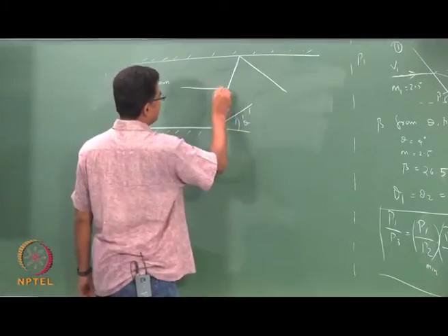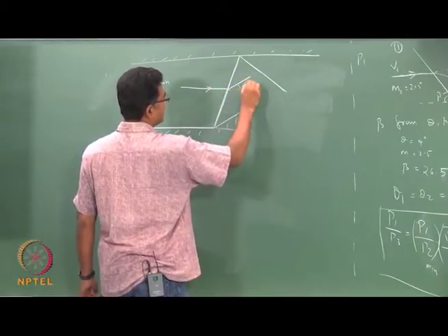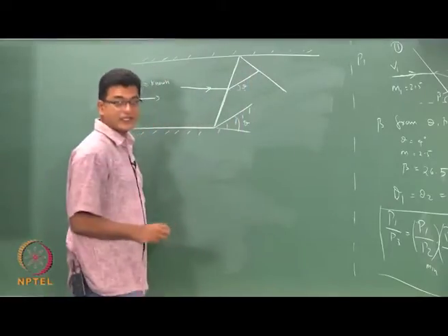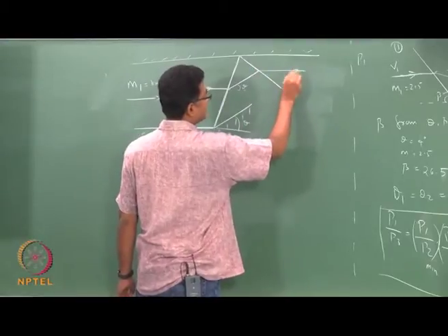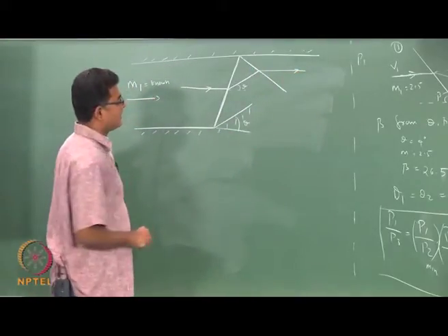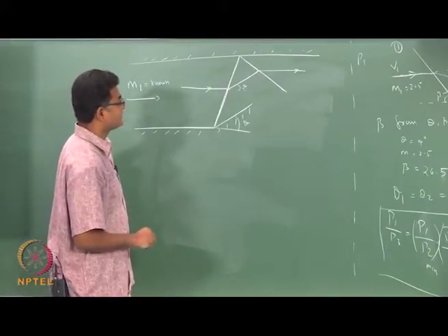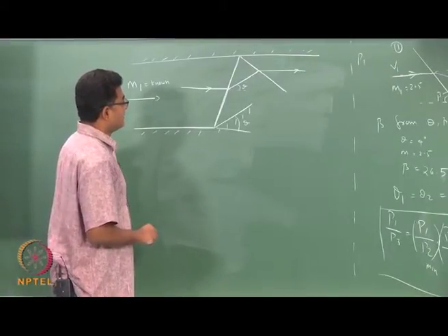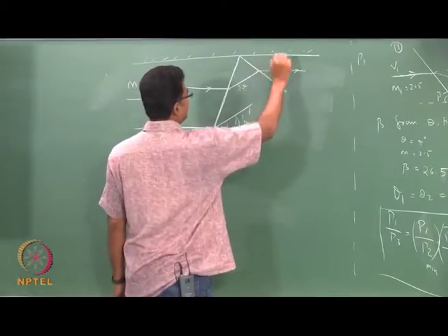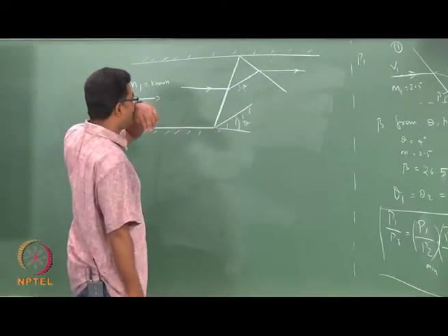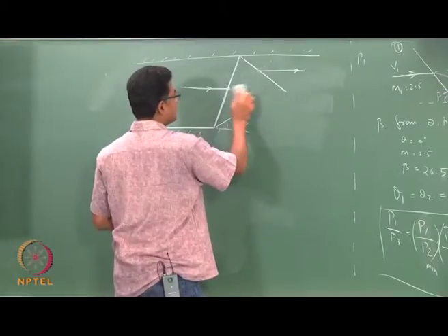So, this velocity vector turns by theta degrees, goes and hits the second reflected shock, then again turns back to the line parallel to your surface. Okay, so this is not normal to this.